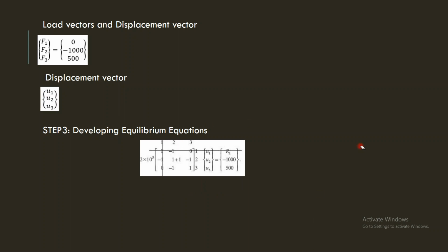Here also, the first thing is to initiate with the stiffness matrix. For the stiffness matrix, you need to go through the particular nodal degrees of freedom, that is 1, 2, 3 and 1, 2, 3. Why is it 3 cross 3? Because we have 3 degrees of freedom, U1, U2, U3. I need to give the numbers for these locations.